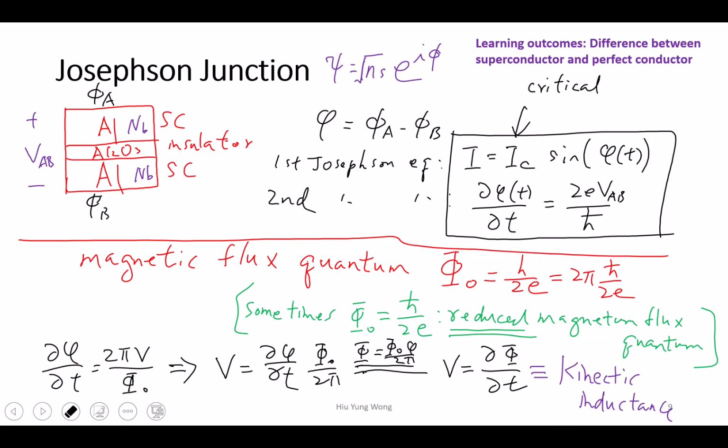That's all I want to say. Maybe I also don't understand this well. But the most important thing is you come up with an equation as if I have an inductance, and that inductance is kinetic inductance. Actually this happens in your regular device also, your LC circuit at room temperature. But it just turns out that the regular inductance is way larger than the kinetic inductance it has.